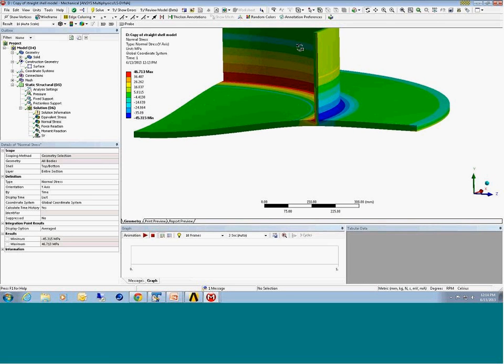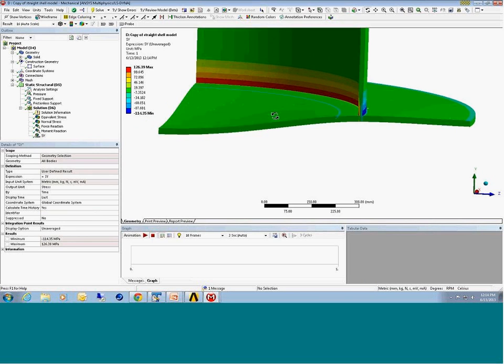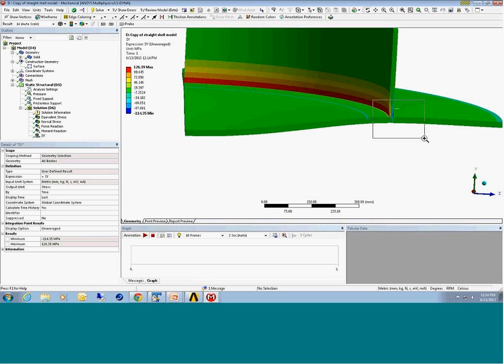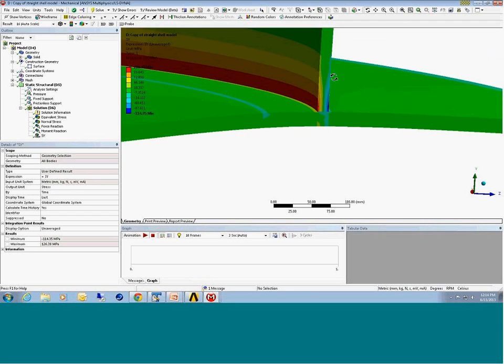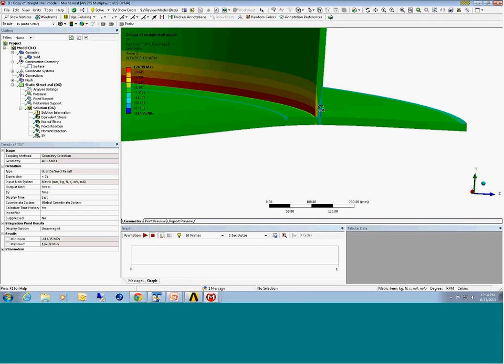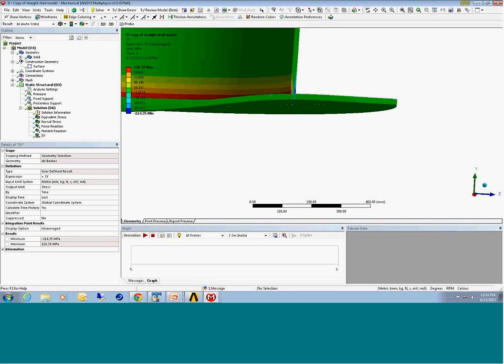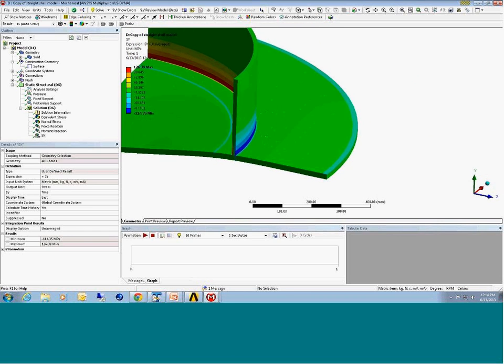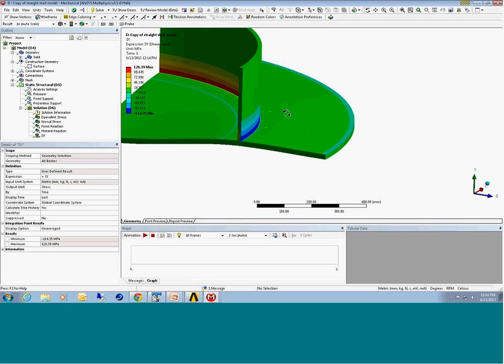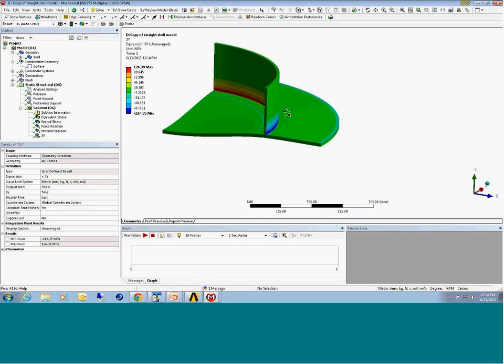The other option is I could take a user-defined result for just this vertical plate, and again, I can predict the stress there, and that stress may be somewhat relevant, but now maybe I'm picking up a little bit of a stress concentration. So again, not necessarily the most accurate result that I want to plug into the nominal stress calculation. Since the nominal stress calculation is based on forces and moments, the easiest thing to do is extract forces and moments from my finite element model.